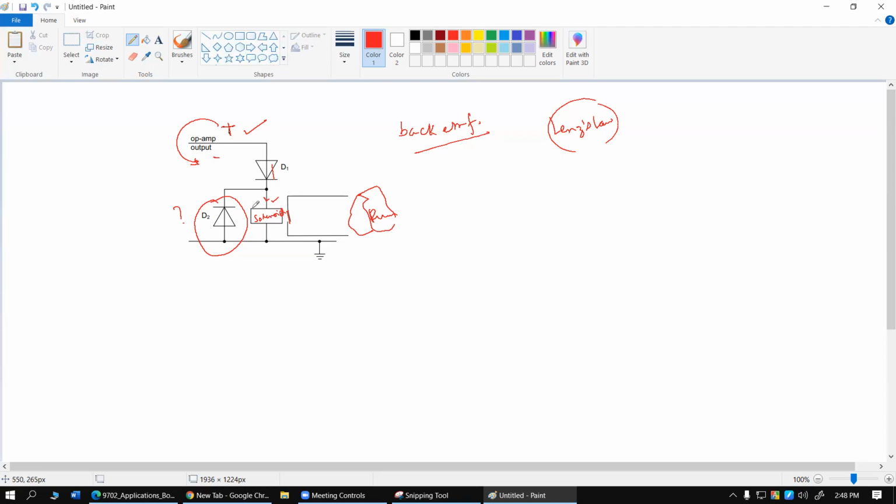In this case the solenoid will produce a positive voltage over here and a negative voltage over here. This EMF that the solenoid produces happens for a very short duration. It is only produced in the solenoid coil as long as the current is undergoing a change. So for the duration the current flow drops from maximum value to 0, this solenoid will produce a pretty high voltage.